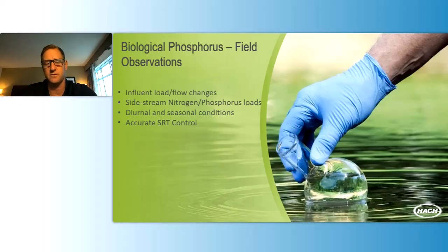Sometimes when we think about phosphorus removal, or even nutrient removal in general, we don't think that how we manage our solids is as impactful as it is. And maybe we continue wasting in certain manners throughout our system, and they might not be adequate, especially at low levels for phosphorus removal. There's competing biology. If we're trying to remove forms of nitrogen and phosphorus, and we're doing that both biologically, there are some real considerations and challenges that we run into.